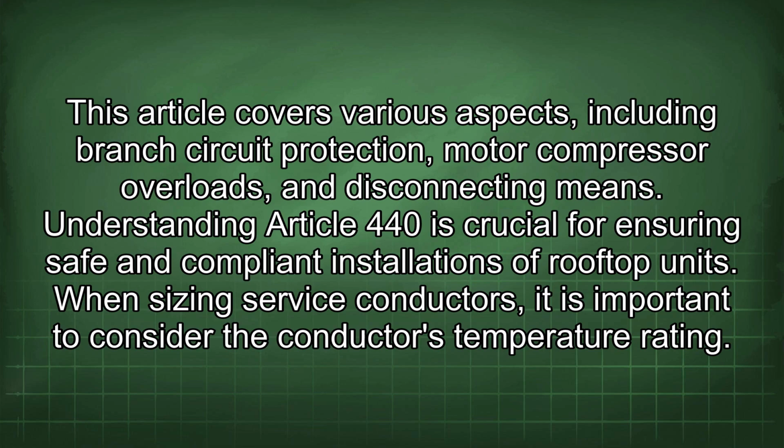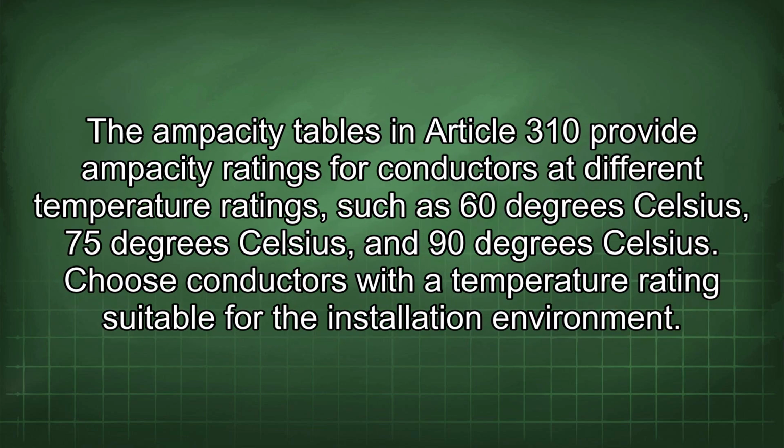When sizing service conductors, it is important to consider the conductor's temperature rating. The ampacity tables in Article 310 provide ampacity ratings for conductors at different temperature ratings, such as 60 degrees Celsius, 75 degrees Celsius, and 90 degrees Celsius. Choose conductors with a temperature rating suitable for the installation environment.